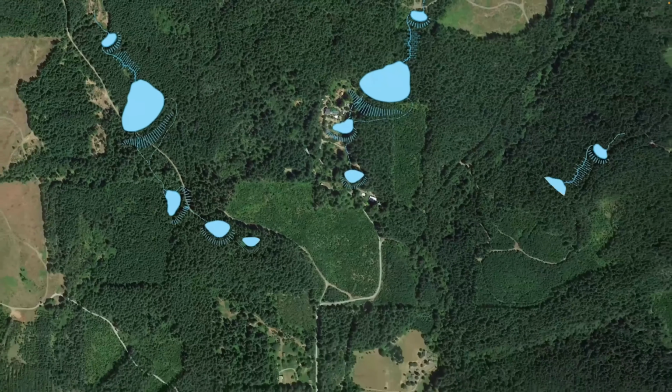Very importantly, this pipe should have cutoff collars installed along its length. And what these do is they prevent flow from moving along the pipe and eroding along the pipe and creating a tunnel through the dam. The proper and long-term well-being of the cutoff collars is really important. People will pour concrete forms around the pipe as it is laid along through the center of the dam. You can also use rubber collars that slide along the pipe. And if it's a steel pipe, also weld cutoff collars.